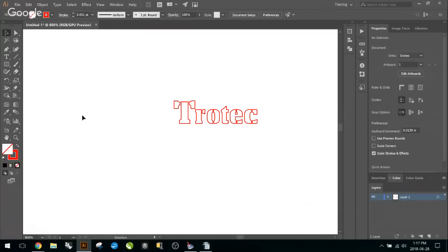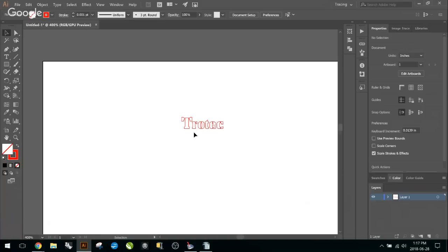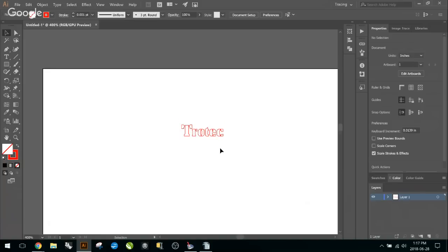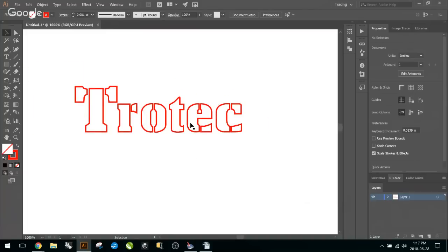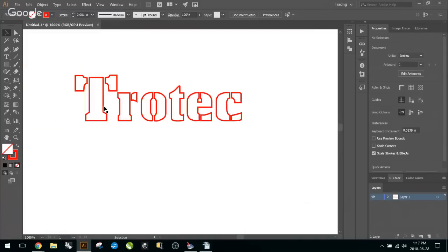There's a couple of questions as well. If text is overlapping, how do you remove the inner cut lines? For example, when cutting out text, I need to be able to cut the outline of all the letters, but not cut inside the text I'm cutting out. However, there are cut lines within the letter. So this is why we suggest using a stencil font here.